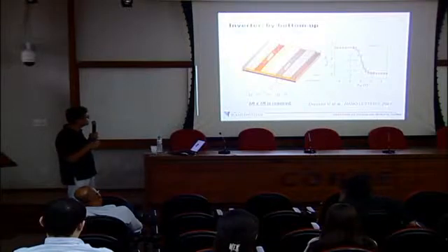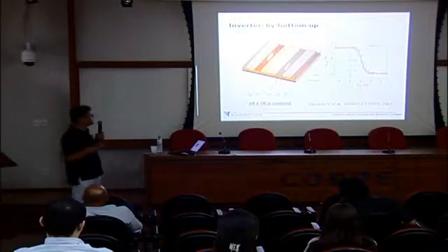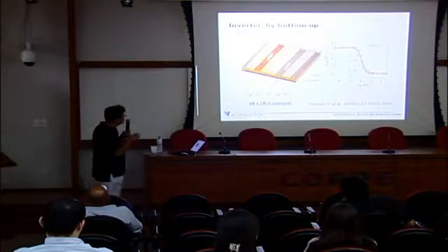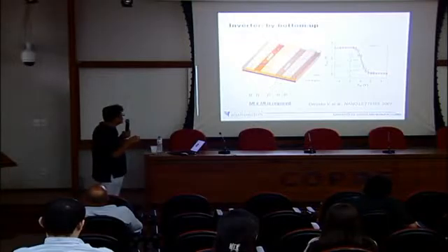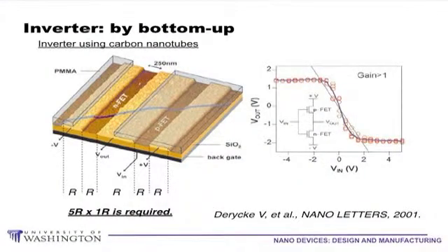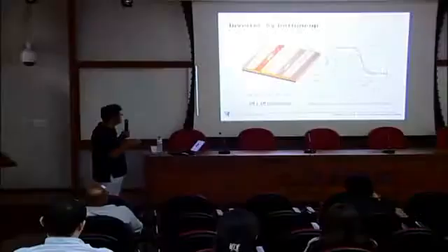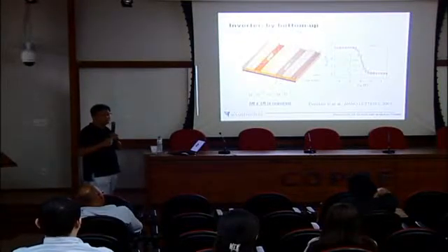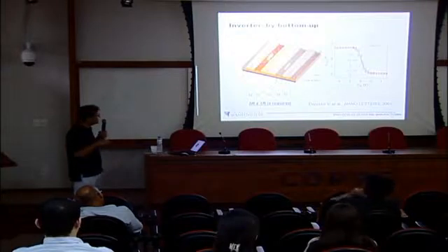Right. So in this case, we used 2 times of lithography because we defined this electrode first, and then at the second step, we have to define this polymer layer. Okay, so 2 times of lithography, and through this direction we use the 5R, defining the electrodes gap and electrodes. That's a 5R, and through this direction only 1R is required. Right? Then the total area is a 5R square.